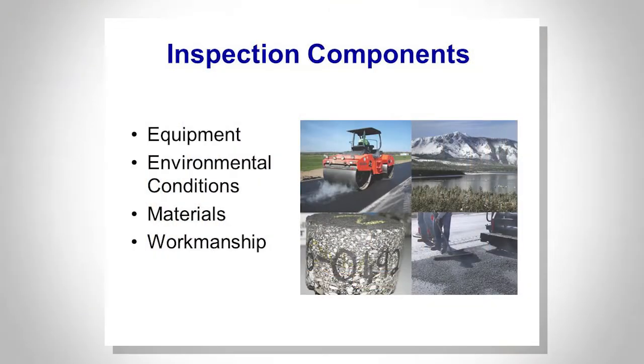Okay, inspection components can be a variety of things that you may need to look at to make sure that they meet your requirements, like for equipment, backup alarms on trucks. You want to try to avoid backing up over people, which in the past couple of years has been a rising number nationally, so be careful there, especially with your workers on site and or moving traffic. Moving traffic doesn't seem to be that much, but if you're actually out there, you can quickly not even hear the backup alarm sometimes.